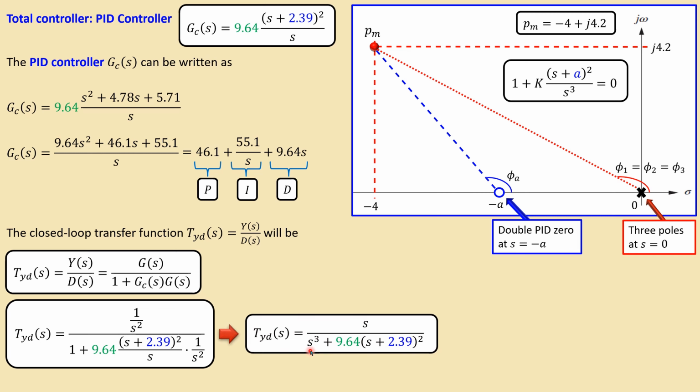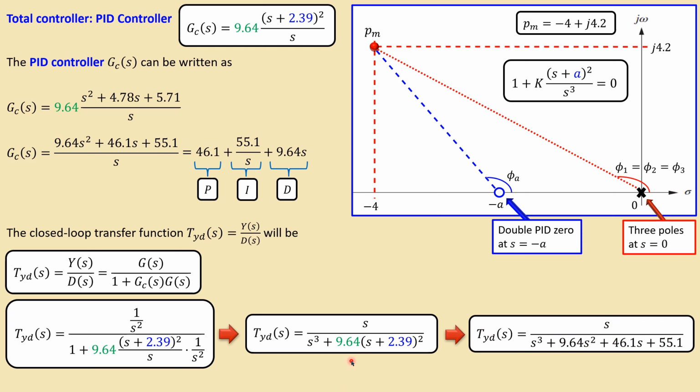Now even more simplification, because we want the denominator as a polynomial that we can use later on in our zero placement approach. We have discussed this also in the previous examples. You will get this. You can see it's a third order polynomial, and the s is still in place in the numerator. So the step from here to there is, I think, straightforward, but let me remind you again. I will multiply the numerator and denominator by s cubed. So I will have s cubed here, 1 times s cubed, and the rest is of course what we have here.